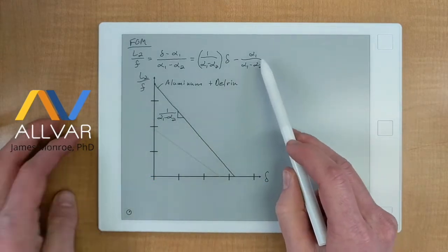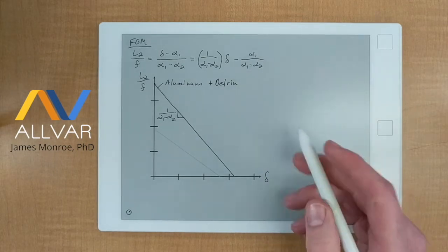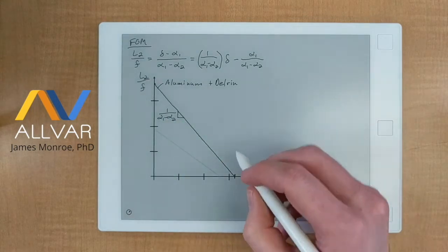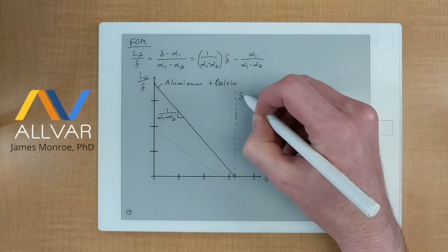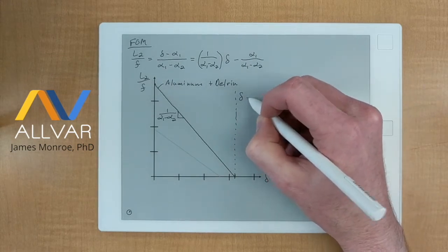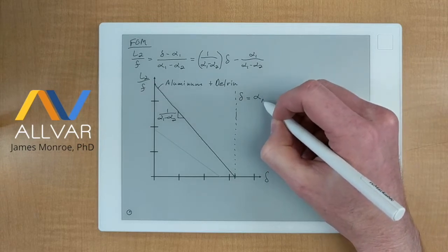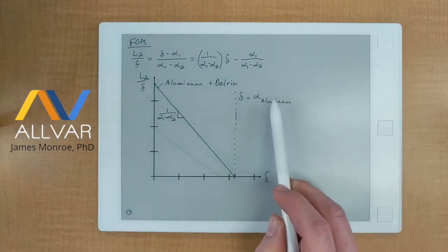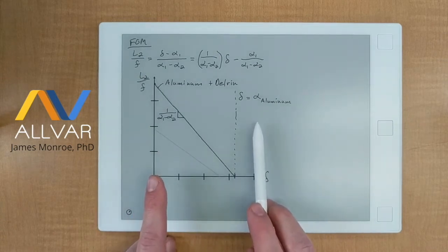And this term, everything becomes 0 right here. So L2 over F becomes 0 at the point where the coefficient of thermal defocus is equal to the coefficient of thermal expansion of aluminum. That's that condition where the focal length is equal to the length of the outer housing.